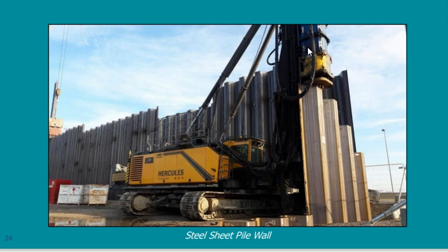It starts pushing this section into the ground, and once it reaches the maximum depth that it can reach, they move to the next one. So they finish this one, they go to this one, and then this one, and this, and this, and this, till they finish a curtain. It will be a wall-like system.